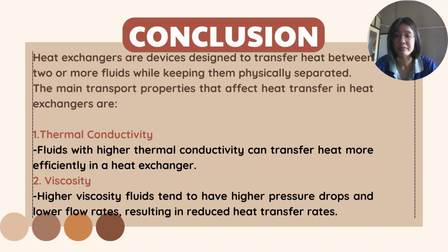It represents the rate at which heat is transferred through a material by conduction. So fluids with higher thermal conductivity can transfer heat more efficiently in a heat exchanger. Secondly, viscosity. Viscosity is a measure of a fluid's resistance to flow. It affects the pressure drop in the heat exchanger and the overall fluid flow characteristics. Higher viscosity fluids tend to have higher pressure drops and lower flow rates, resulting in reduced heat transfer rates.